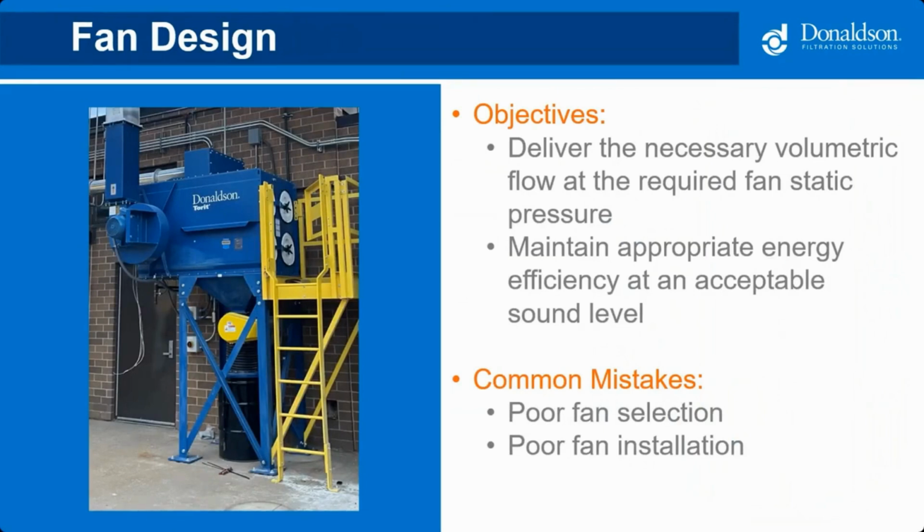First of all, a fan must deliver the necessary volumetric flow at a required static pressure to drive the operation of the system. Since collectors will operate with clean or dirty filters, the required airflow must be maintained over a range of operating static pressures. Secondly, the fan you select should be able to deliver the desired static pressure and airflow with appropriate energy efficiency and at acceptable sound level. Fan challenges generally fall into two categories: poor fan selection and poor fan installation.